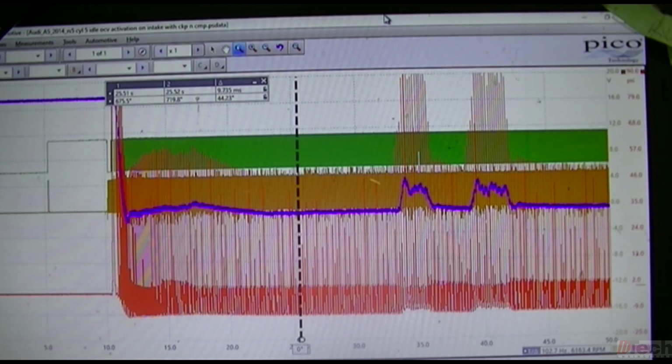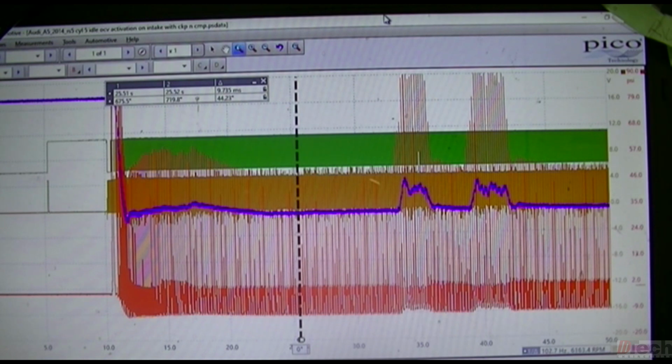One of the main reasons why I wanted to also do this was to compare both intake cam phasor advancement in amount of degrees to see if it was the same or close enough to the same bank to bank, to also try to help narrow down exactly what is going on as far as why the code would keep coming back.